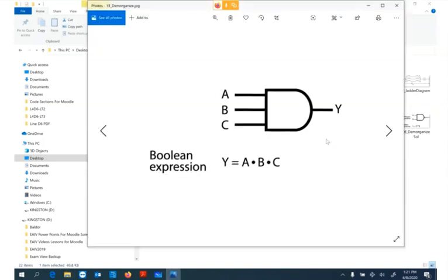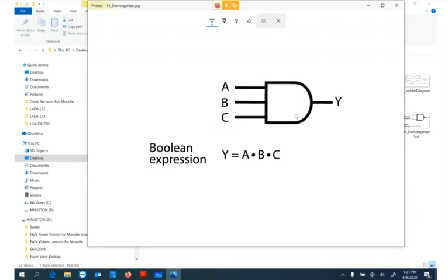So if we look at this 3 input AND gate, there's our A and B and C. It's not really a multiply. That's just the way it's said. You don't have to put the dots. So in order to De Morganize this, we change this here to an OR instruction. Then we negate all the inputs and the output, which they did in the next picture.